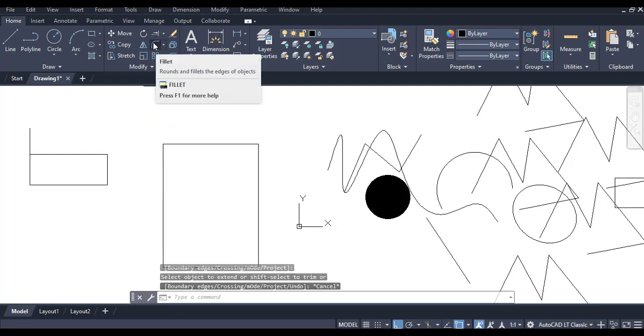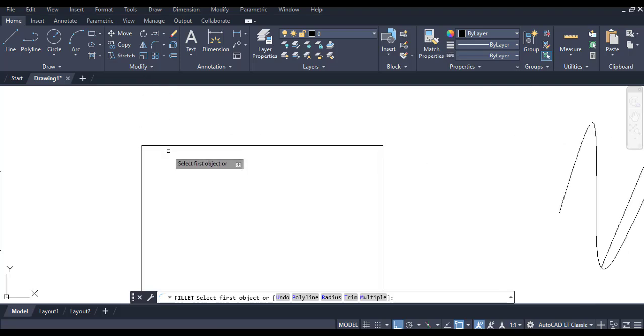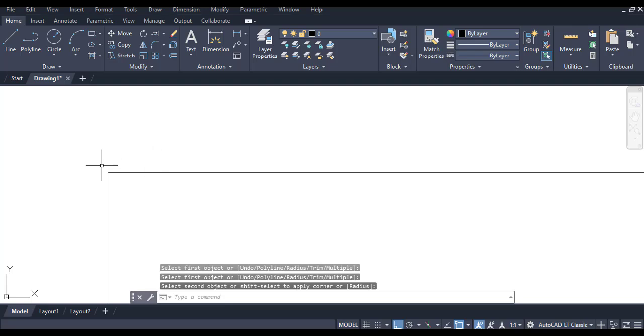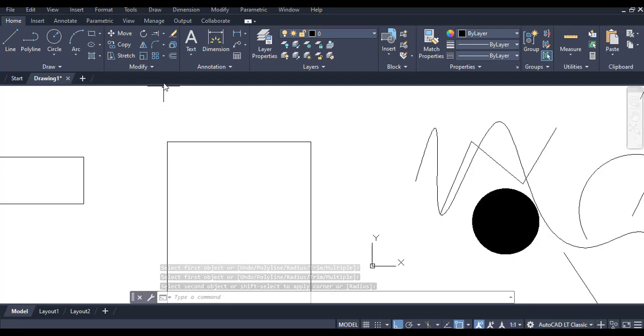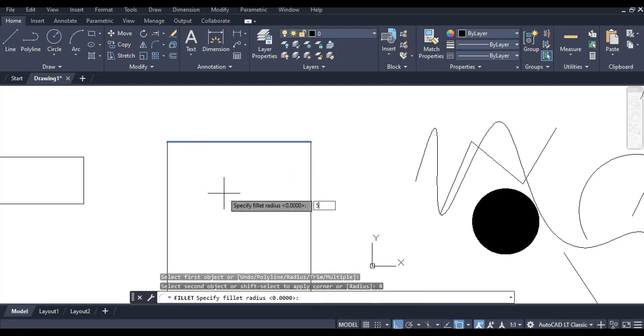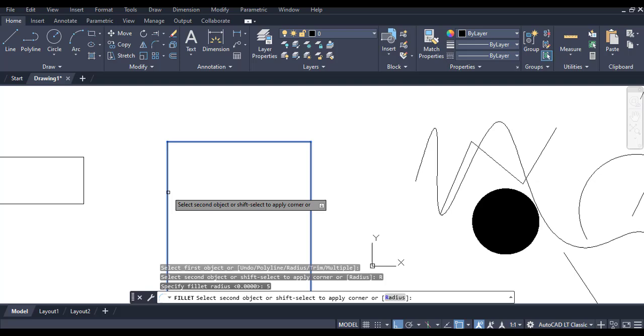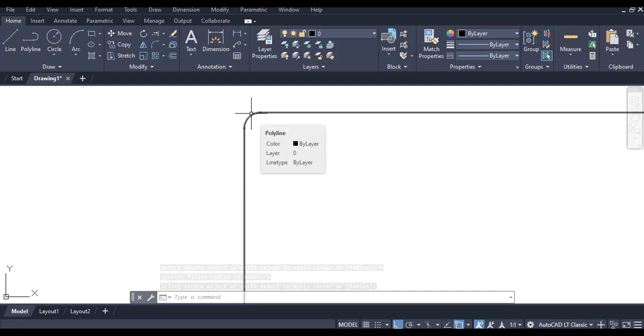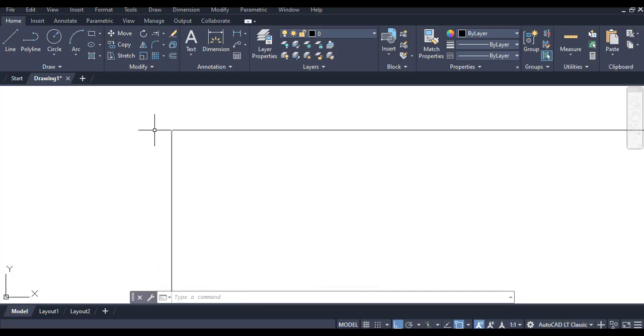Then the next one is what we call a fillet. A fillet helps you create round curves on edges. So if I want to fillet an object, I click on the 2 points where I want to create the curve like this. Now, why you are not seeing anything here is because I've not set my radius. So I'll click on fillet, click on this, right click, then click on radius, probably make my radius 5. Since we've not set any unit here, I'll click on that, and now you see the curve, right? Now we're going to do the settings later on. I'm just showing you guys the tools we work with. You get the point.